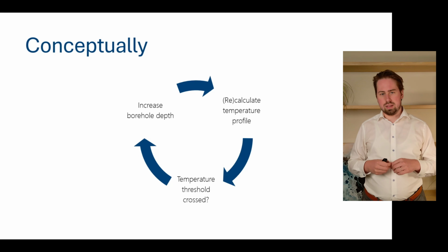This is the second chapter of this seventh part, and we will be taking a look at our first method that is typically used when we're designing geothermal bore fields, namely calculate the required borehole depth. Now, this methodology, although a little bit self-explanatory, basically assumes you start with a given configuration. For example, you say, well, we're going to drill 4 boreholes, but you want to know how deep they should be in order to make sure that your entire building demand is fulfilled with the geothermal system while staying within your temperature limits. And conceptually, that looks a little bit like this.